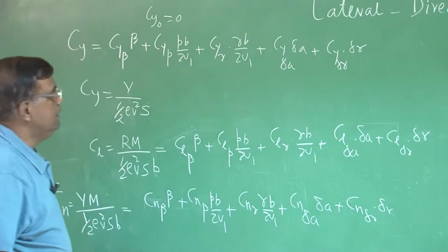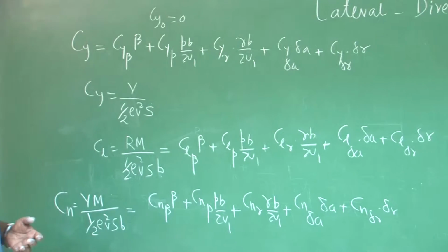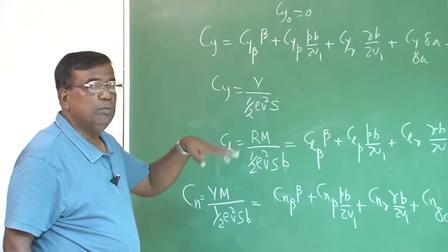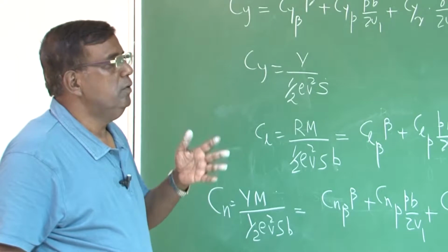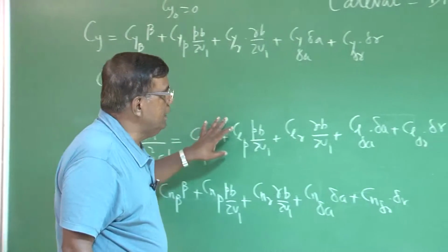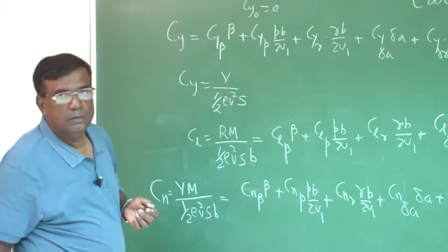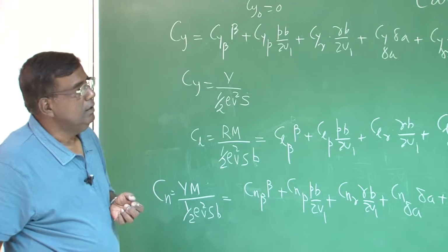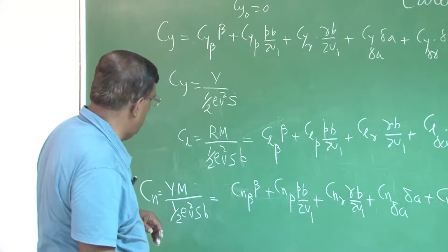Please understand, this sort of an expansion is strictly true for low speed and moderate performance airplanes, where we are assuming everything to be linear. Today's modern aircraft are very high performance with high rates and high angle of attack. So there, writing or expanding this in terms of a linearized concept may not be true, unless you cleverly, judiciously, locally linearize it. But there are different ways of handling it. So that should be kept in your mind all the time.